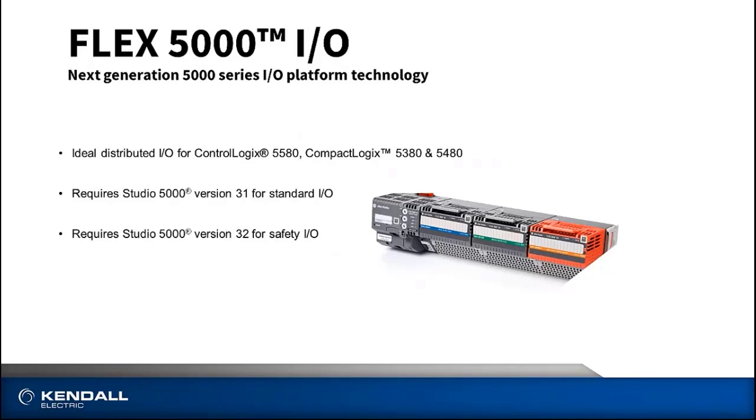Similar to what I mentioned on the Compact 5000 I/O, this Flex 5000 is compatible today with the ControlLogix L8 or 5580 PLCs and the CompactLogix 5380 and 5480 PLCs. It is not compatible with any of the other PLCs at this time.